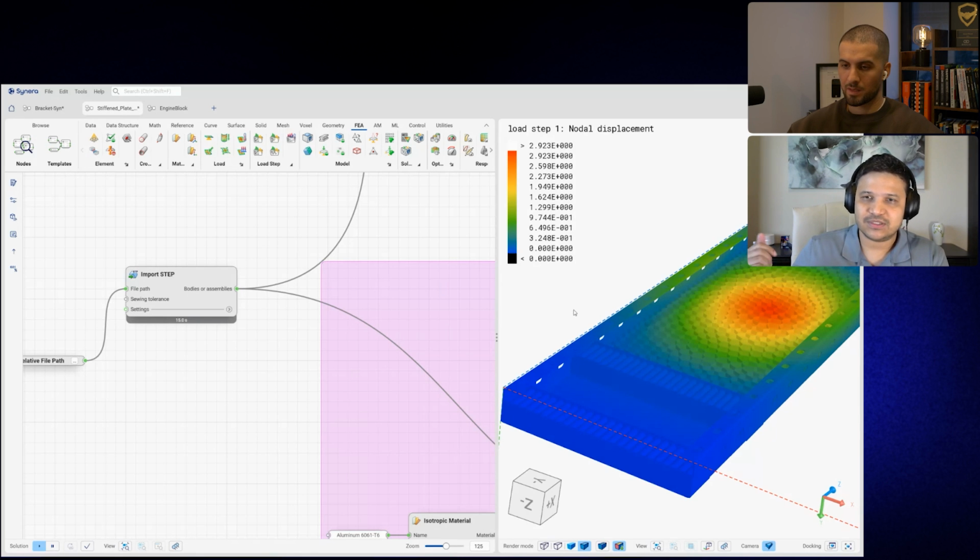What we do is, our Intact technology is based on classical FEA methods, where we are using the same classical methods in performing FEA on the non-conformal mesh. But what we do is mesh the space around it. This allows us to take the geometry in and out, like we put a different geometry and keep the same boundary conditions and properties in there.